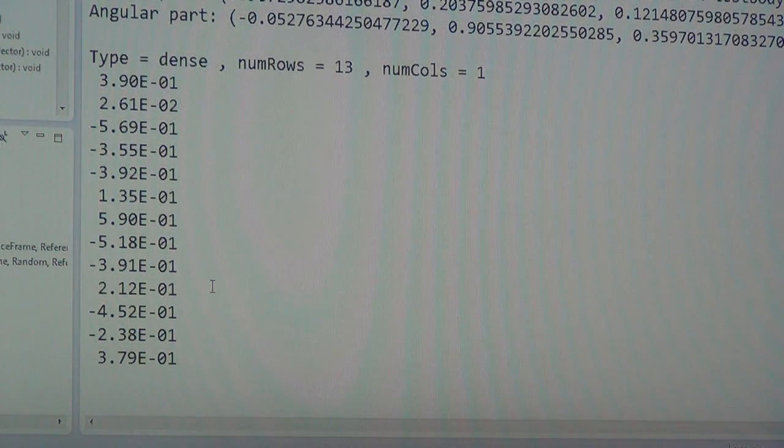So the joint velocity vector was just a twist, and the thing that the force space joint parameter that results in power for a twist is a wrench, right? So it always needs to be the case that wrenches dotted with twists are powers, and joint torques dotted with joint velocities are powers. Otherwise, it doesn't make sense in terms of units.